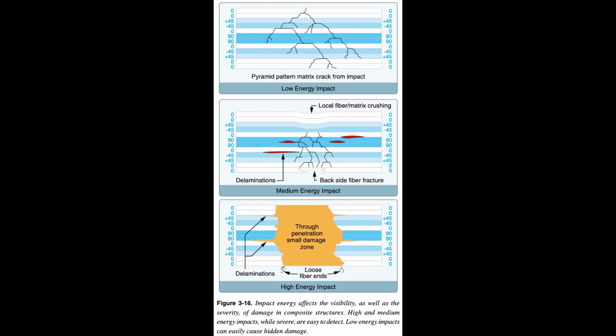If an impact results in delaminations, crushing of the surface, or a puncture, then a repair is mandatory. While waiting for the repair, the damaged area should be covered and protected from rain. Many composite parts are composed of thin skins over a honeycomb core, creating a sandwich structure. While excellent for structural stiffness reasons, such a structure is an easy target for water ingress, leading to further